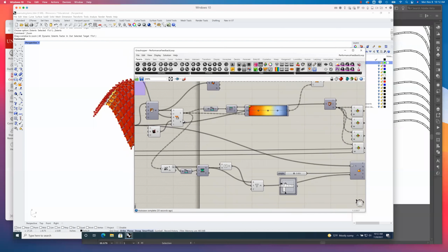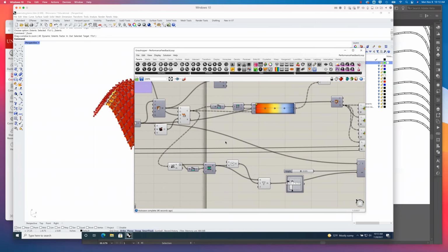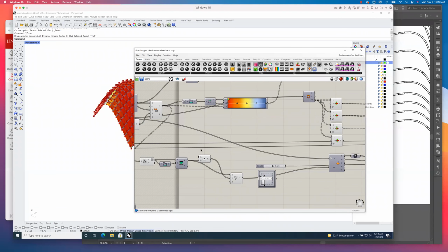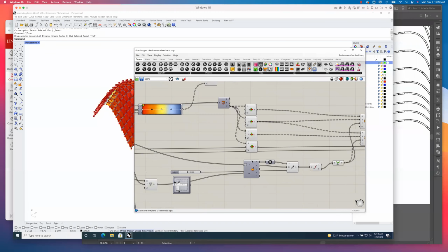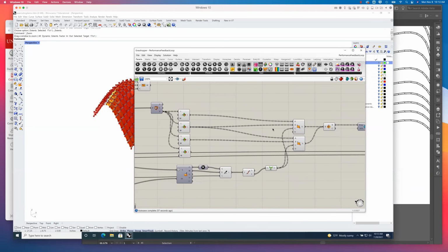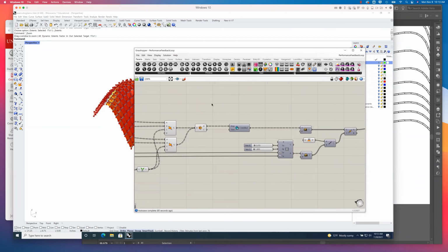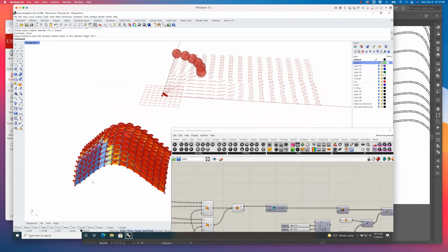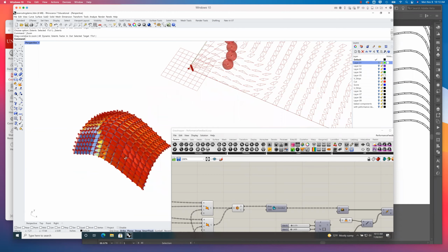Oh, yes. Okay. So again, taking these energy values and not just plotting them out as color values so we can see what they are, but using those values to inform the parameters for generating the shading geometry itself, right? So in this case, we're not just picking a height and a UV value willy-nilly, but we're letting the data actually make those values for us, so that what we end up with is a gradient where we get really closed cells over here, and really open cells over here, and they gradient out across and in between.